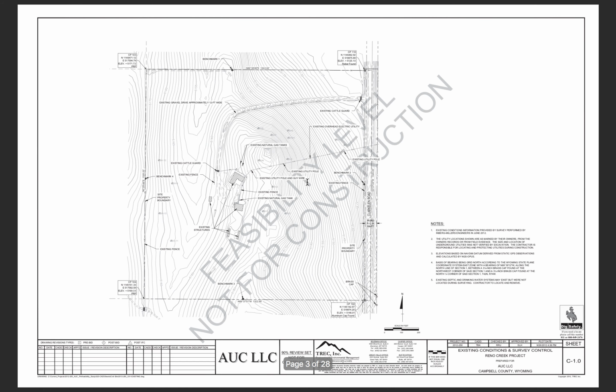This site plan is what's existing on the current building site and also shows the survey control. So we have a bunch of buildings here, some power lines, some natural gas tanks, and then the current elevation. As surveyors, if we notice here, as we saw in the legend, this is a benchmark. It has a leader telling us that, but we could also look back at the legend if we didn't have a leader, and we could know that these were current benchmarks.